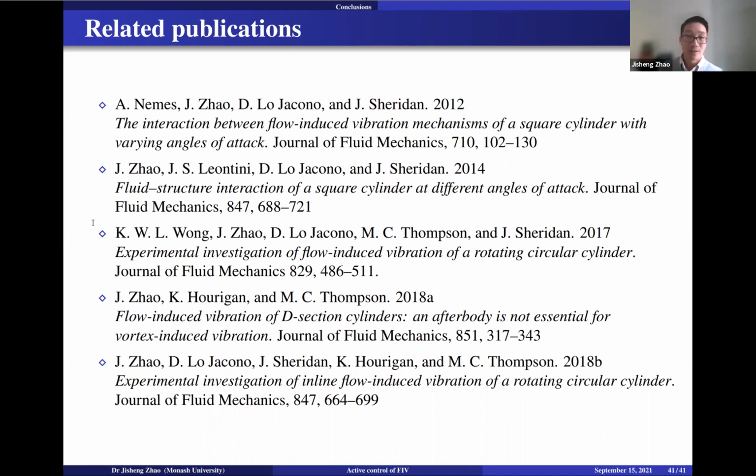Yeah, that's why we introduced the body perturbation. We try to affect the surface speed, and thus we can change the vortex shedding mode somehow. We also looked at the feedback control of the sphere. We find it quite interesting. We can adjust the phase between the Magnus force and the structural vibration position, say the cylinder position, and then we could control that quite successfully.